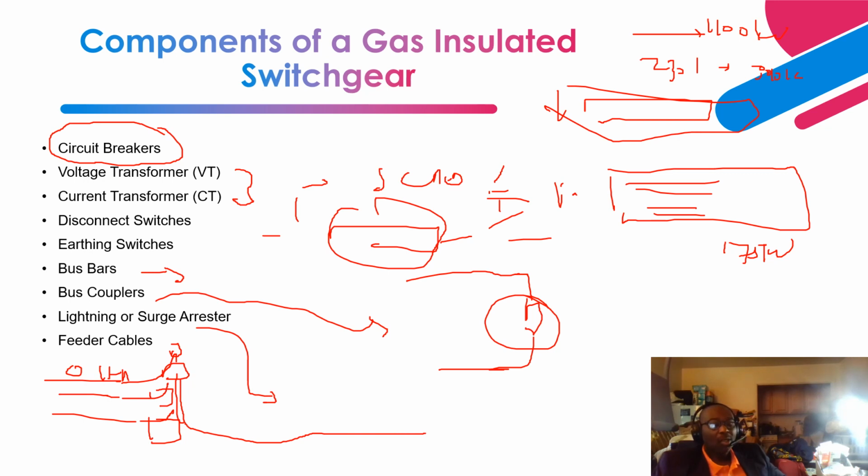What is done at the interface is that there's something they call a traveling wave. This interface has a high impedance. There's an impedance change, because you have an overhead line and a feeder cable coming in here. At this point it's seen as a change in impedance such that it requires a surge arrestor to be installed, to be able to withstand the high voltages due to the traveling wave.